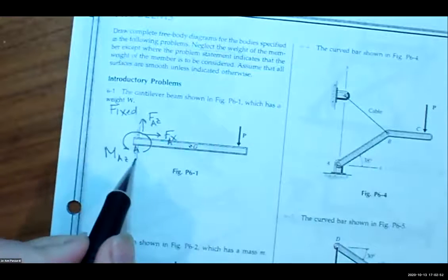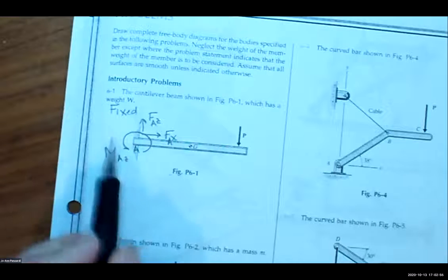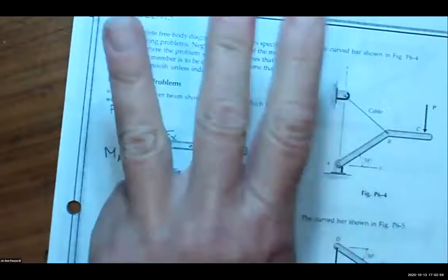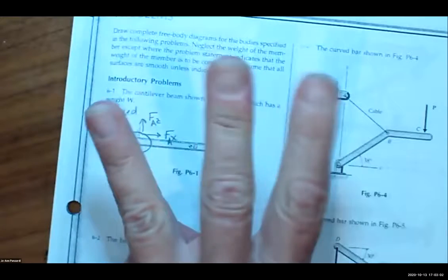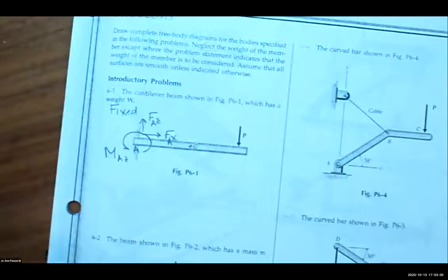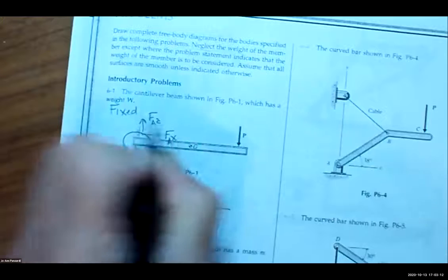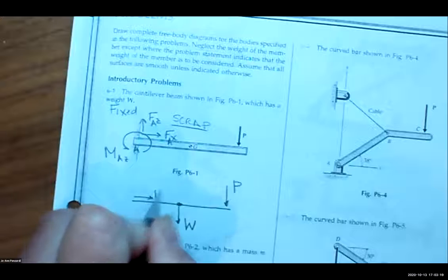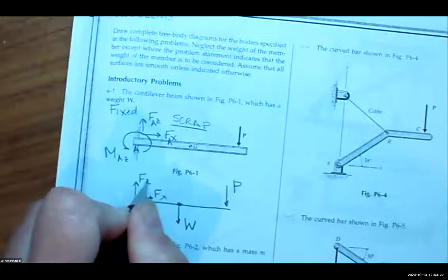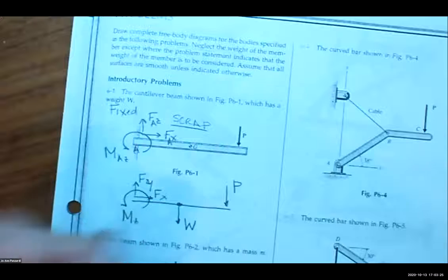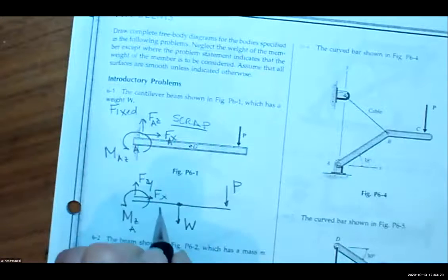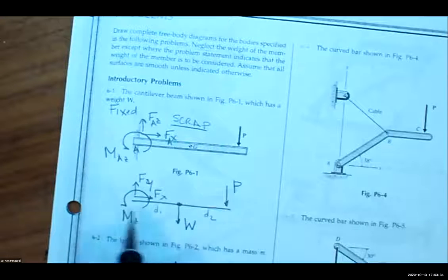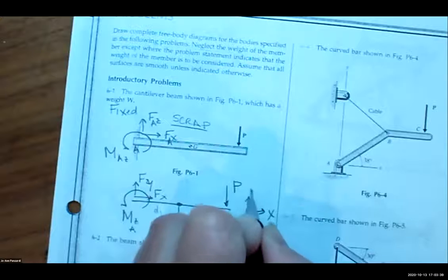So what I'm drawing is the reactions at that fixed support. It's a two-dimensional problem. It at most could resist 3 different motions: translational in the X, translational in the Y, and rotation about the Z. So my free body diagram then would be this object. I would have its weight going down. This right here is scrap. I would have the P here. I would have a force in the X, force in the Y, and a moment about the Z. And had this had distances, I would have had distances on here too, because a free body diagram of a body has to have the distances and also has to have our axes.